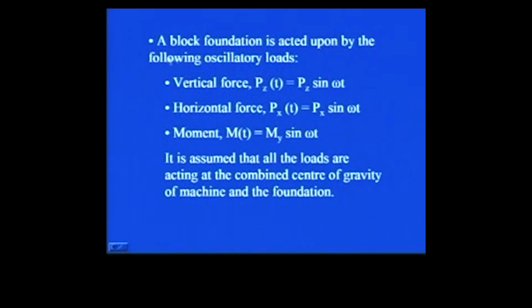So in this case, a block foundation is acted upon by the following oscillatory loads: a vertical force, which is a function of time, Pz sin omega t; then a horizontal force, also a function of time, Px sin omega t; and then a moment, My sin omega t.